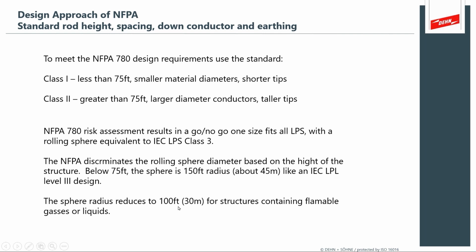NFPA does also recognize that structures with flammable liquids would benefit from a shorter rolling sphere radius, and that's an important aspect of the NFPA standards.